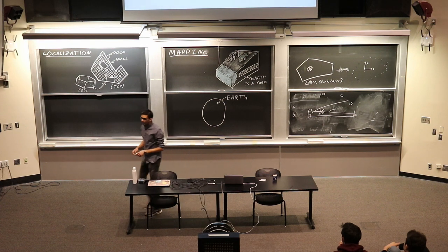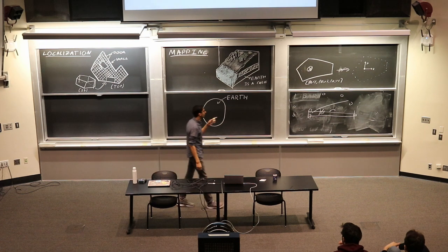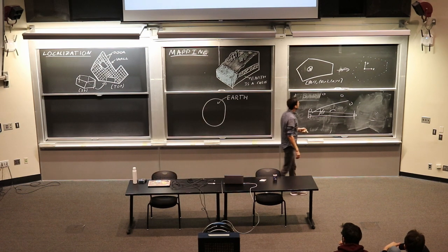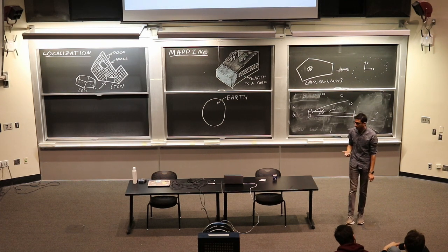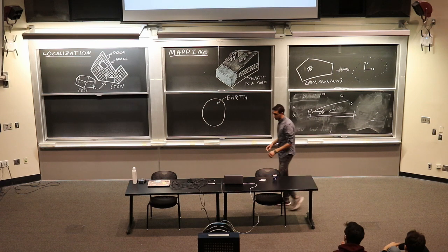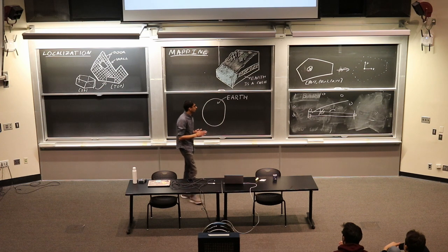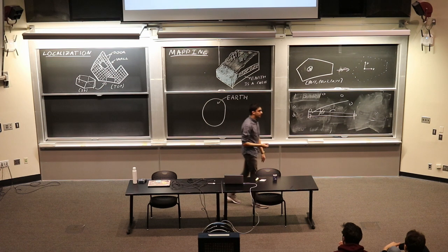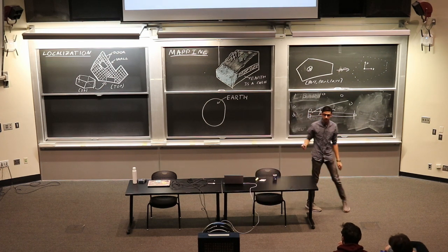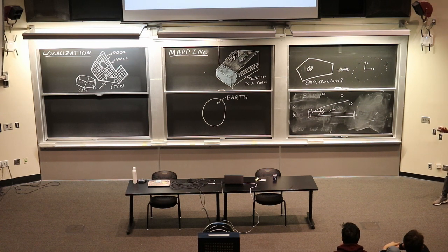And now this is really cool, and the reason it's really cool is because it allows us to figure out with one sensor what our entire environment around us looks like. Because the problem with unknown environments is that the robot has no idea what the environment looks like, and therefore doesn't know what to expect or how to localize in it, right? Because localization requires you to understand your environment. So LiDAR is one of the sensors that allows us to figure out what the environment looks like.